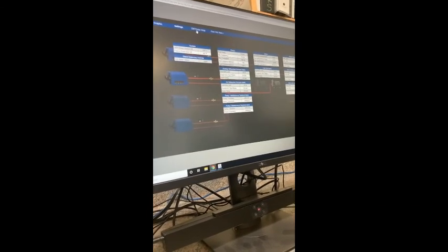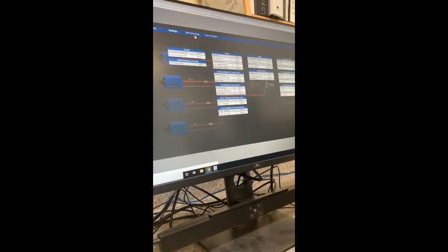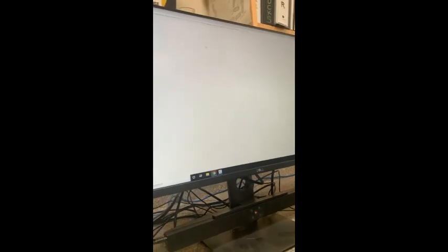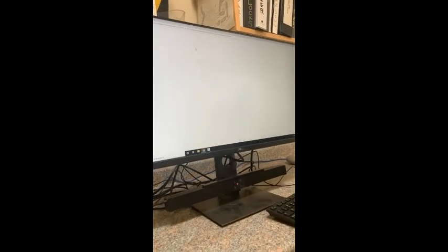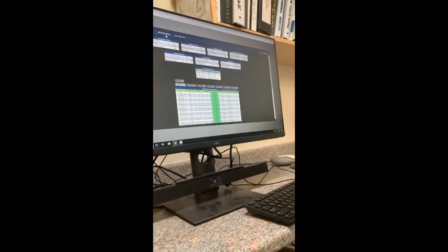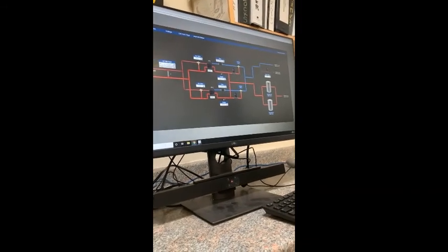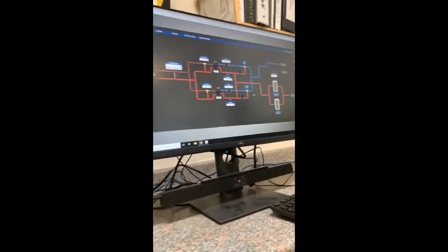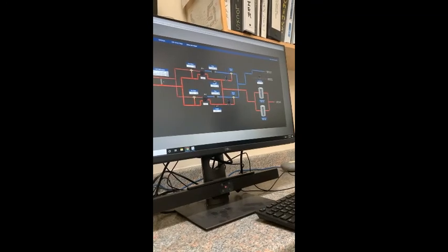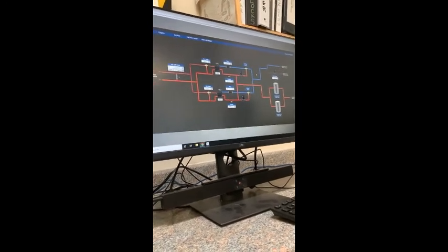And then again, we have the differential pressure requests. It's basically the same thing between this and the chilled water system. It goes out, looks at all the valves, sees if any zones are requesting additional, and then it'll reset the DP up. And then we have a domestic hot water that's off of this, where we're just monitoring all this. We don't control any of it.